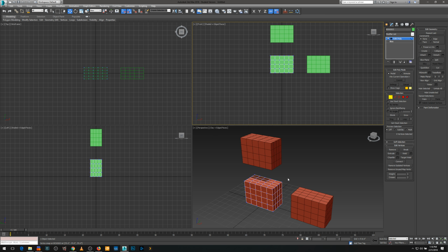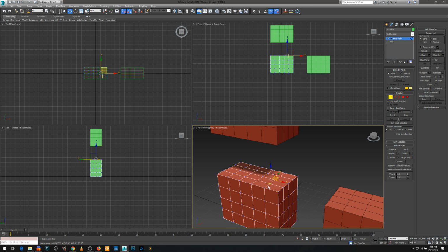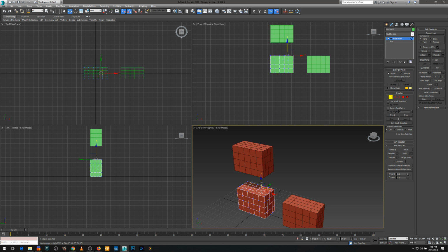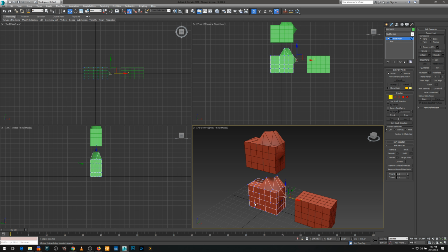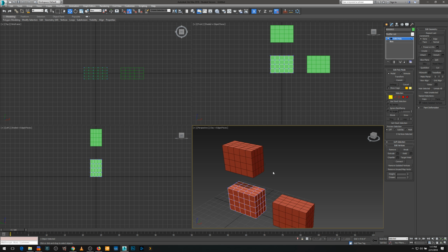So I'm going to say 1, and then I click and drag, and I can grab, or I can click directly onto a vertex. We'll take a couple here. And then once I have a few selected, you can tell because they're in red, I'm going to drag up, right? So the instance on top is mirroring and doing exactly the same thing because it's an instance, not a copy. The copy stays in the original form. So we're going to undo that with Control Z. You could step back, I think, up to 25 times by default.